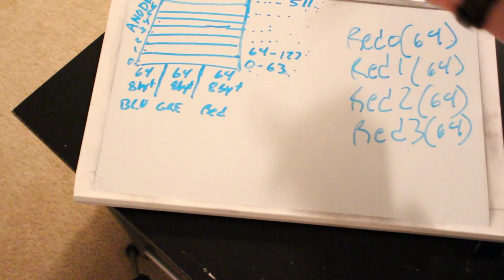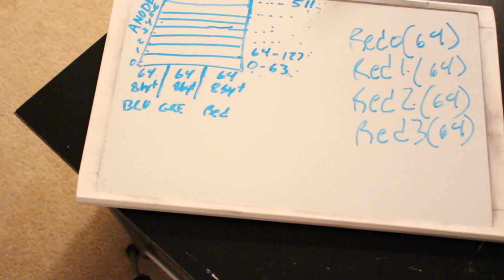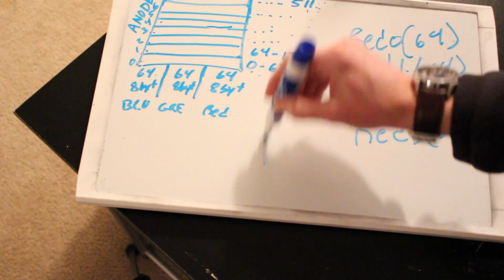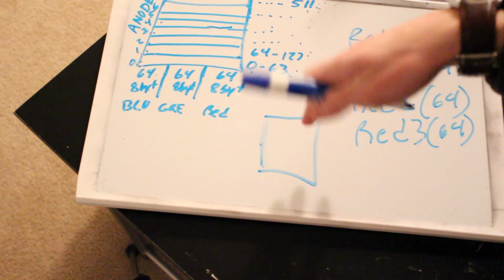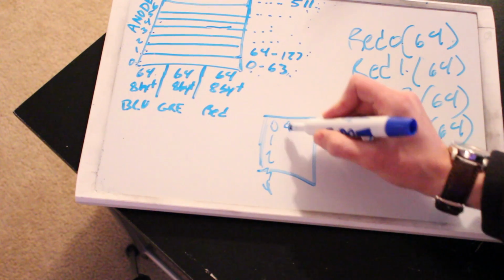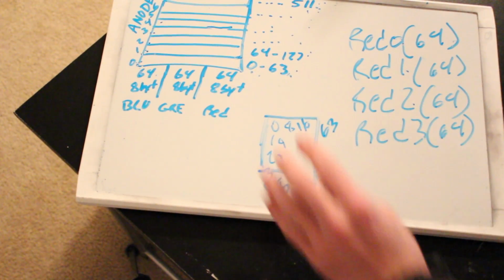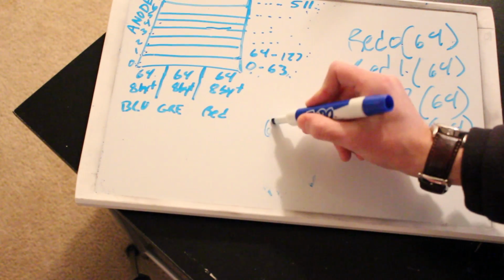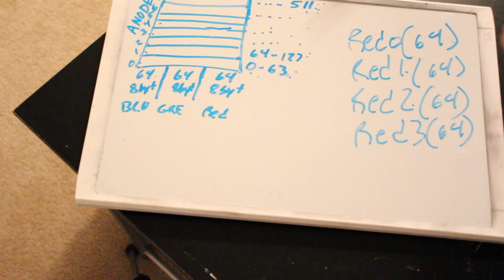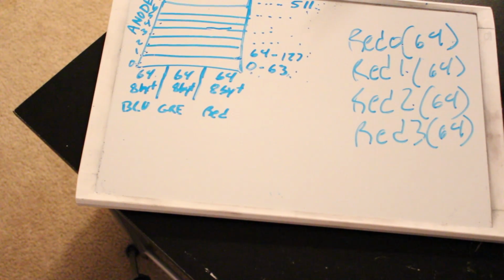And then as it works through the bit angle modulation, and you'll notice you have red 0, red 1, red 2, red 3, 4 bits for the bit angle modulation. Now I'm getting a little ahead of myself here, but essentially what the level row column does is if you looked at the cube face down and you're looking at level 0, it's sort of like going 0, 1, 2, 3, 4, all the way down to 7, 8, 9, 10, all the way to 15, 16, and it's going all the way till it gets to 63, and then on the very next level, it starts out at 64 and continues through. So what we're doing is giving each LED its own bit in memory, so that when we shift out data to it, we will then shift out the bytes according to that level that we know.